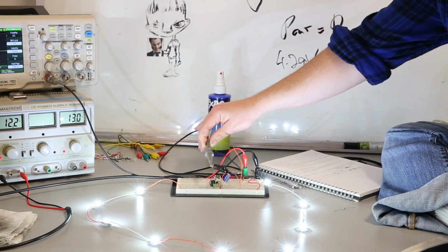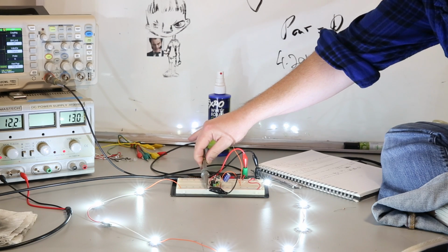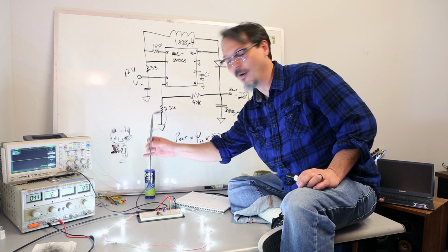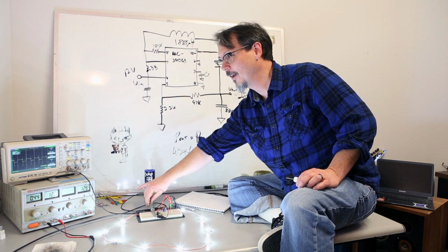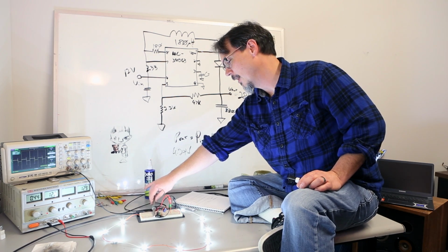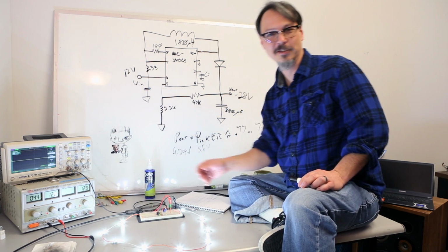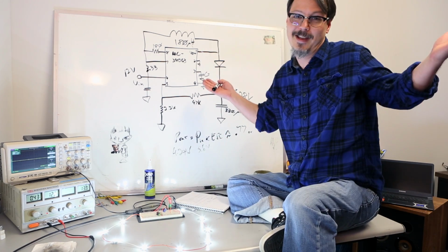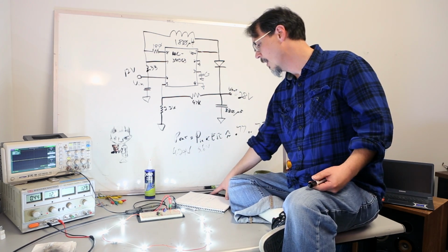You put this thing around my kludge of a circuit, and if you can see the scope over there, this is really noisy, okay? This is not an RF loop, but you can bet I'm picking up a lot of noise, a lot of high frequency spikes. This thing would wreak havoc under certain circumstances, okay? So you want to be more careful than putting it on a breadboard, but hey, I'm breadboarding it, so there you are.